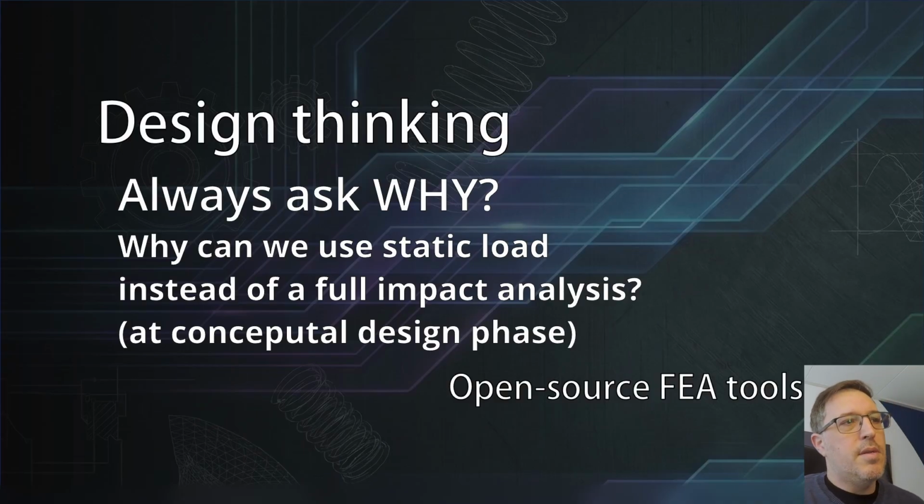I was thinking about it, that in my previous videos I've mentioned as a fact that when we would like to test our design during the design phase, and one of the requirements is an impact requirement, then we can always simplify the problem by having an equivalent static analysis instead of performing a more complex dynamic impact analysis, that will represent the problem in order to help us understand how the design behaves so we can make appropriate changes.